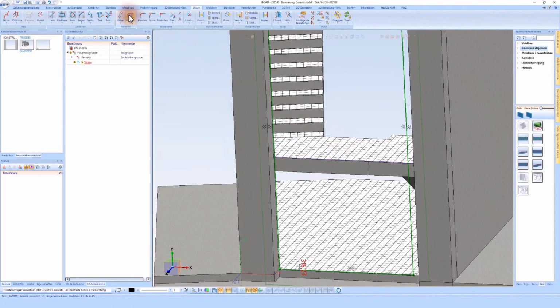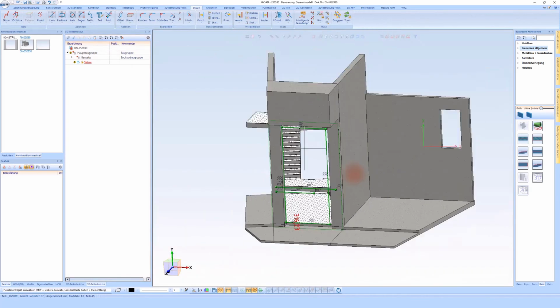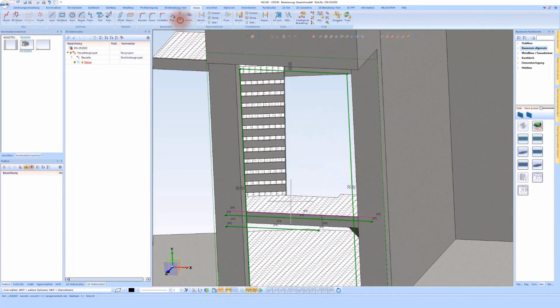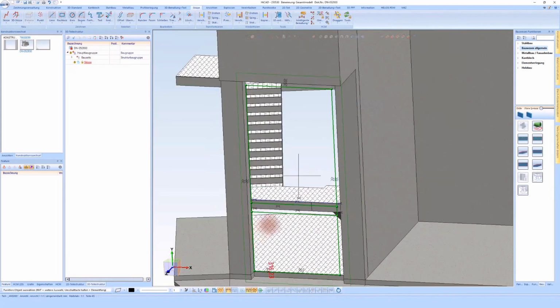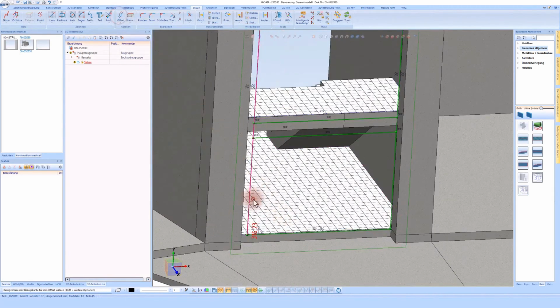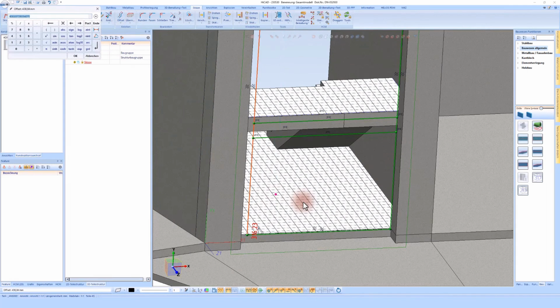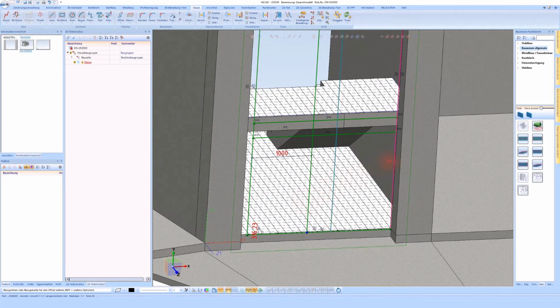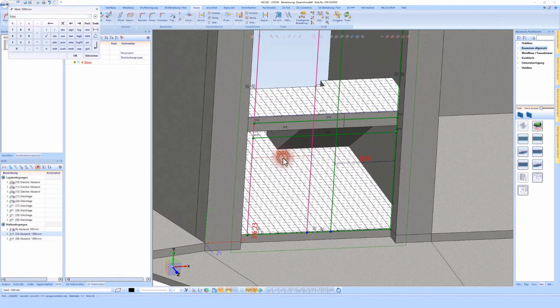Then I would also like to have an edge or a bar here at this height and once at this height. These are my fixed bars where I will also place this right here. Trim to the corners or to the edges. And then in this case, I can simply create my grid division. That means I can go here and, for example, I simply enter 1000 mm from the left and right, once here and once here. I can, of course, change this at any time afterwards.